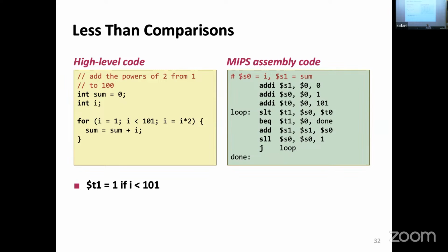And if you go back into the lecture when we were talking about combinational logic, at the very end, we had an ALU, and we showed that it can do addition, subtraction, and, or. And one of those instructions, if you go back in the slides, was this funny SLT. So we use the same ALU to make this comparison, because what we do is subtract those two numbers and check if the result is negative.